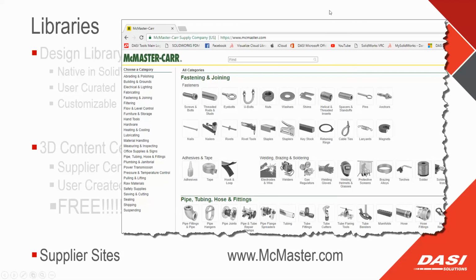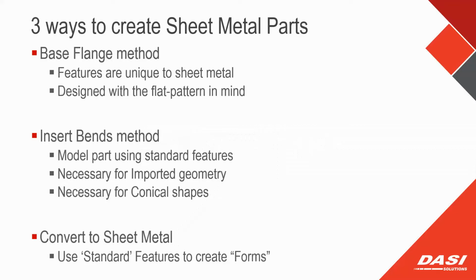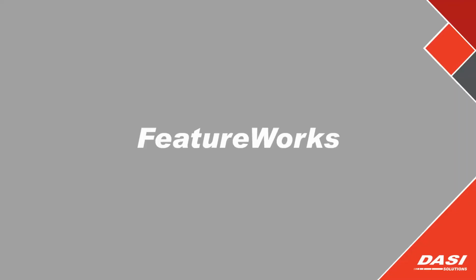All right. So the next thing we're going to talk about here is FeatureWorks. Now FeatureWorks is a feature recognition tool in SolidWorks. Got a little slide out of order here, excuse me, that's not what we're looking for. With FeatureWorks, we get into the creation of our data. And when we're receiving files from other systems, those come in obviously a different way. They're a featureless folder in the feature tree, or a graphical body that's accurate in geometry, but doesn't have any sketch or featured dimensions to it.